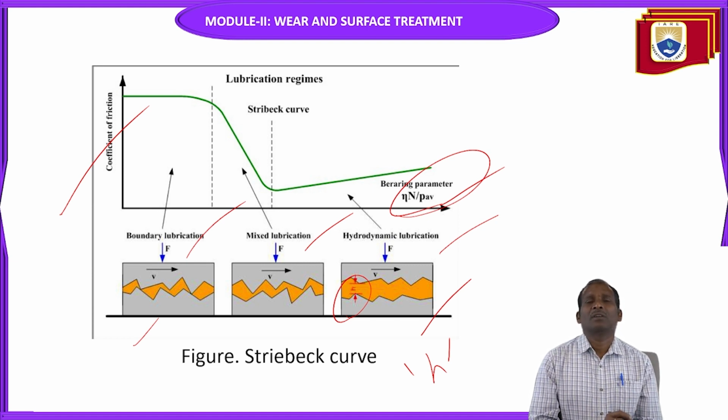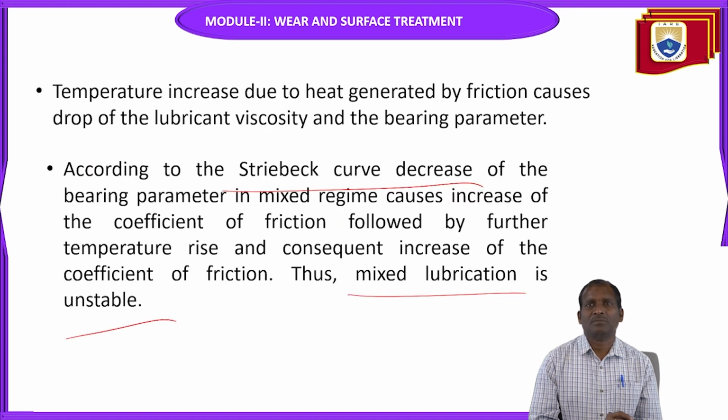So in this curve, whenever the bearing parameter decreases, the coefficient of friction increases, followed by further temperature rise and a consequent increase of the coefficient of friction.